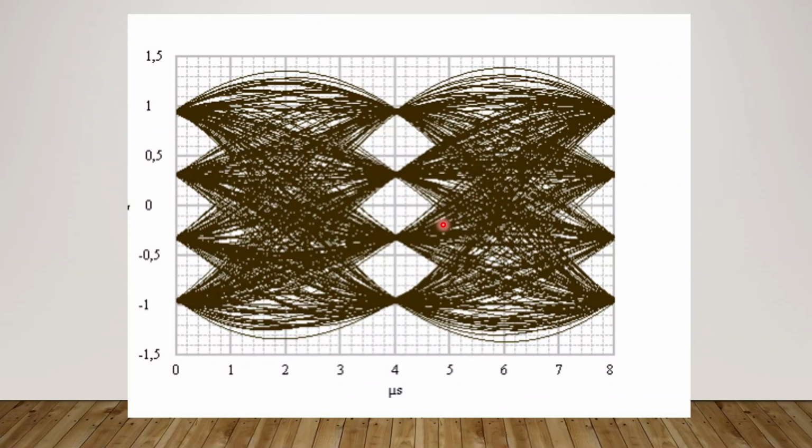So this is the practical eye diagram. It is plotted for M-ary signaling. There are 1, 2, 3, 4, 5, 6, 7, 8 eye diagrams. It shows the eye completely closed, so it is not possible to eliminate the intersymbol interference in this case. This is the practical eye pattern diagram, which is plotted with the help of a CRO.